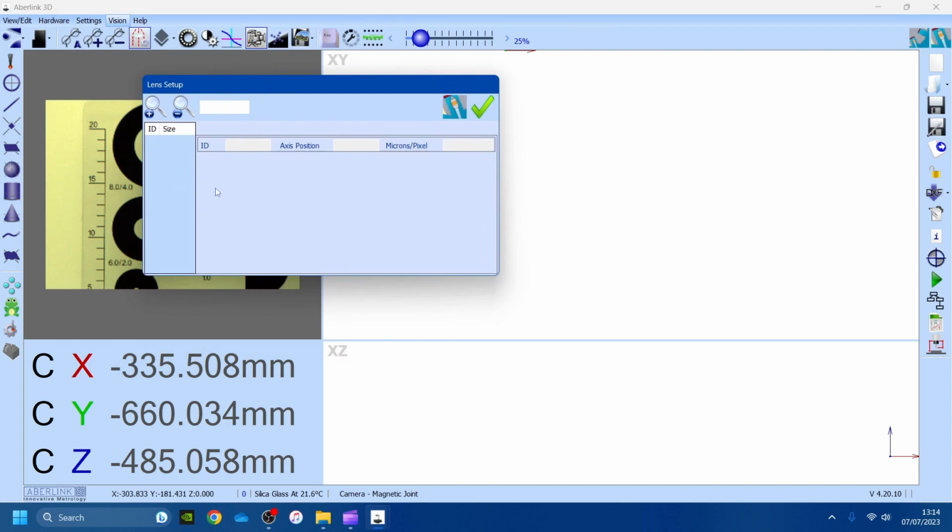So the idea is every time we adjust the camera, we need to create a new ID. You can either use the same ID and recalibrate the camera after every mechanical adjustment, or you can try to create fixed IDs for each different adjustment. I would recommend using a single ID and recalibrating the camera after any mechanical adjustments. This gives it the highest accuracy without any issues.